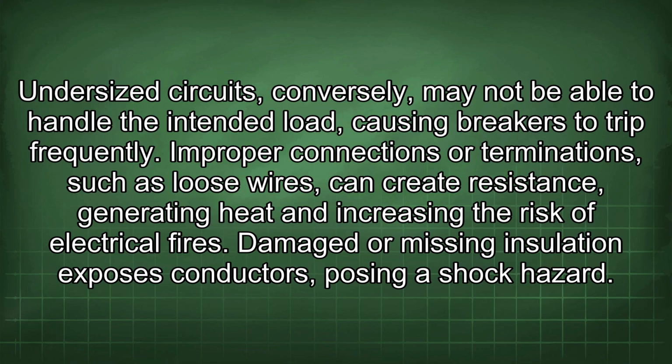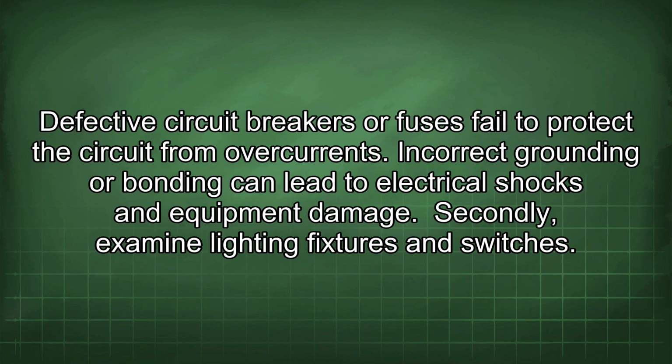Damaged or missing insulation exposes conductors, posing a shock hazard. Defective circuit breakers or fuses fail to protect the circuit from overcurrents. Incorrect grounding or bonding can lead to electrical shocks and equipment damage. Secondly, examine lighting fixtures and switches.